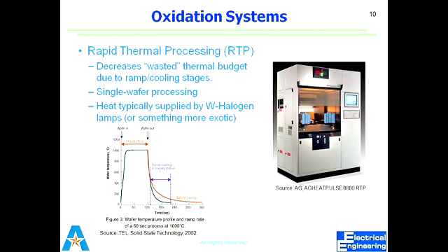The temperature to which you can go after you deposit layers on the silicon substrate. Like once you do metallization, you can't go on to higher temperature processes. So once a particular layer is grown, your thermal budget keeps shrinking down. Like you've used up that much of it, you can't go beyond, say, 300.